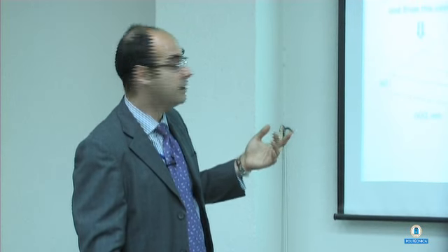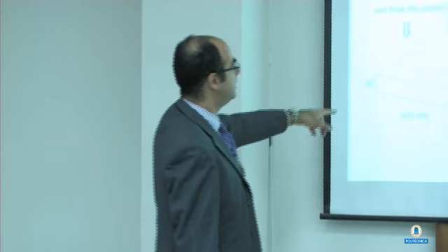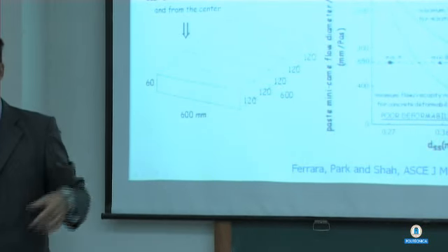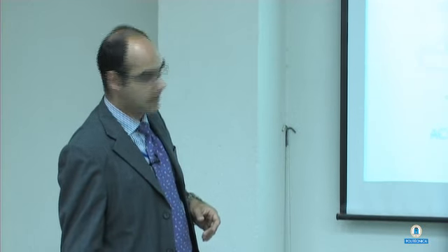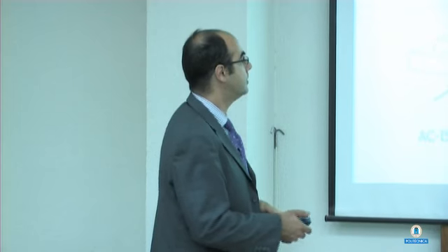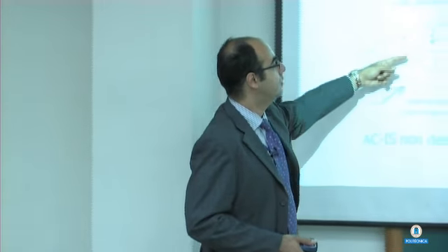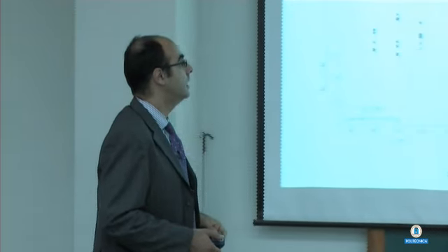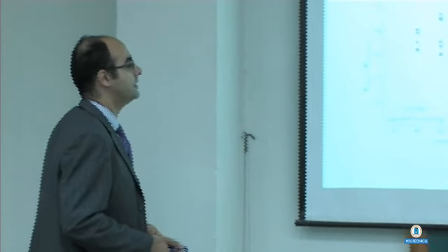We first performed the non-destructive measurements for fiber dispersion, and after that, you see here, we cut 5 beams from here and we tested them in 4-point bending. This is the layout of the measures that we took with the alternate current impedance spectroscopy method for fiber dispersion. Basically, we took the measures in 2 directions to check for the fiber orientation. And here you can see some of the results.